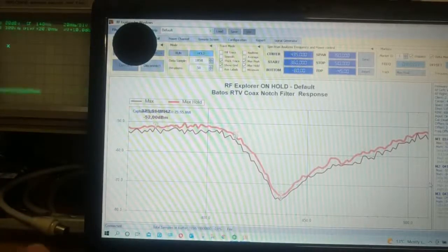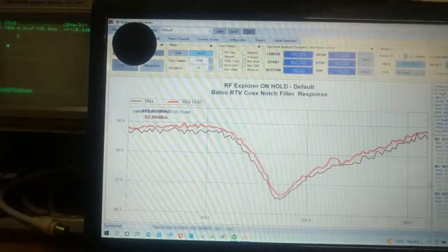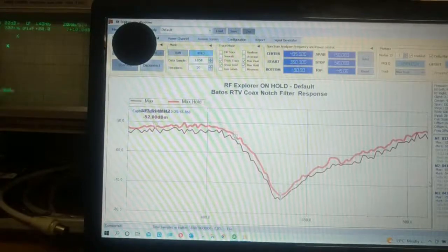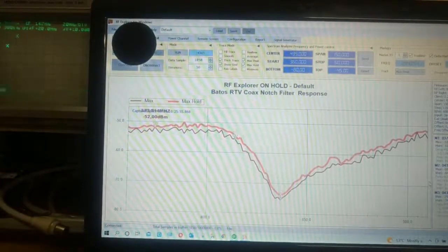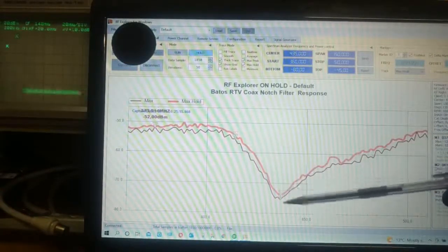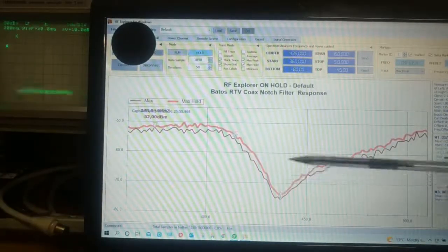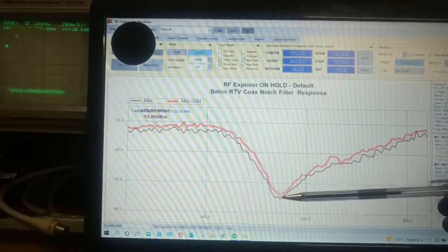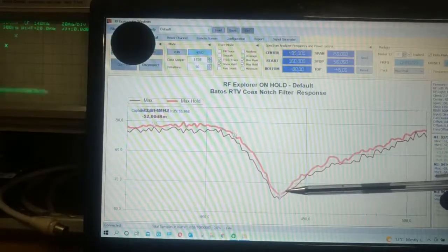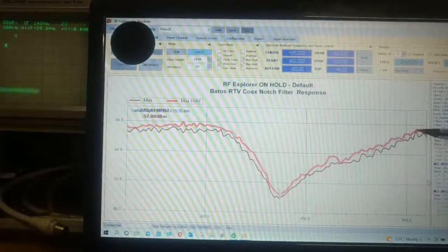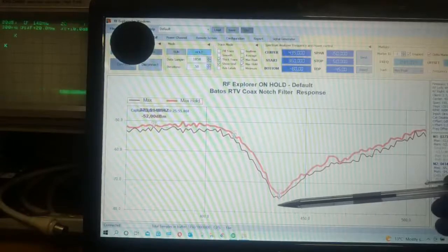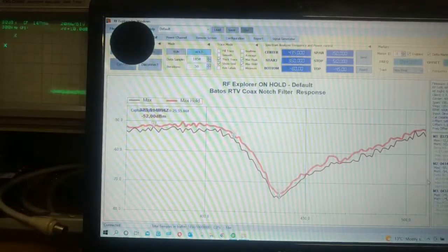Now, any coaxial cable or any cable has capacitance and resistance and inductance. And basically, that forms the impedance. And at specific frequencies, depending on where the cable is cut, like in our case, that particular cable is cut at a specific length. And at that particular length, the impedance is the highest. The resistance is highest. Basically, inductance is the highest, and so on. And that gives us the highest impedance, which in turn gives us the highest attenuation of the actual unwanted signal. And of course, then what it does, it just lets all other signals through.